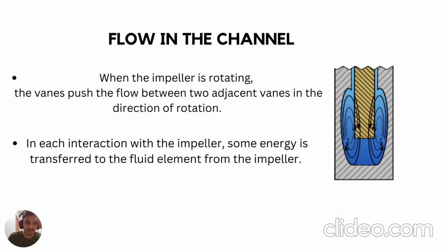The unique shape of the flow channel with its two interconnected side channels generates a vortex flow in the two cells, as you can see in the diagram. On each side of the web, the interaction of the tangential flow due to the vanes and the vortex due to shear action causes a helical flow in the channel. See, this is the helical pattern. Due to this flow pattern, a liquid element gets into the space between the vanes many times in its passage from inlet to outlet.